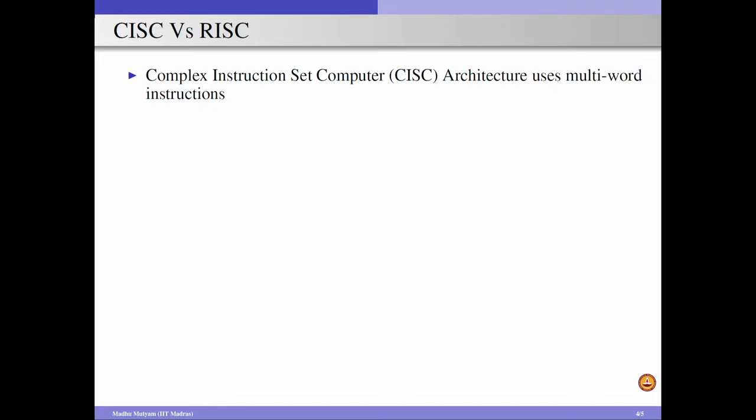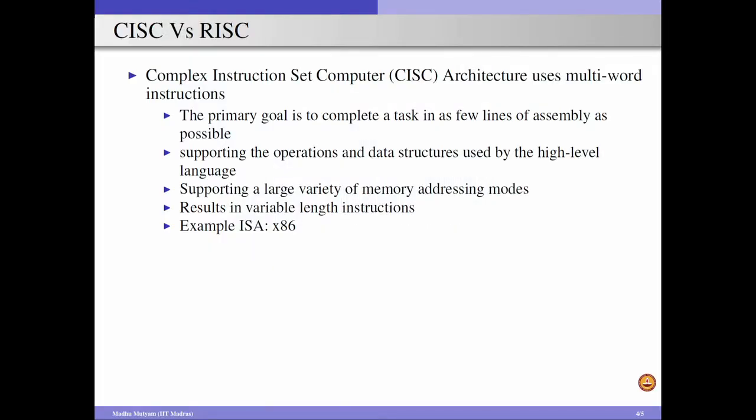If you recall our instruction encoding discussion, we know that variable length instructions typically fall into the CISC type of ISA. So what was the main reason the CISC architectures were proposed? This is a very old ISA, and in those times the main memory was very premium. So the main objective was to reduce our code size.